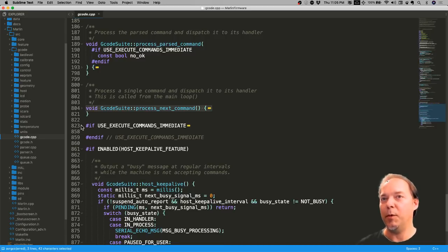And so we actually have the ability to use G-code just like a function, because when it comes back, it restores all the parameters that might have been there from the G-code you're currently calling it from. And so you can carry on just as if nothing happened. It's really cool, and I highly recommend if you have some feature that you need to implement, and you can do it by using existing G-codes and calling them like functions, go for it.